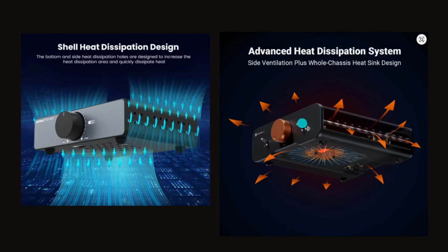You remember, here is a picture of why it is not possible. There is no airflow. You need a fan. Yeah, then you need a fan, and then you can go with a higher power. Actually, with the same board, you can put in a more aggressive cooling system, and then you can have this high power out of it. Yeah, the same 48 volts, but a 10 amp power supply, and you need additional cooling.